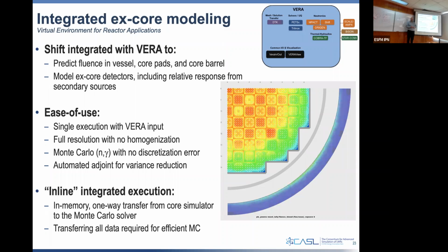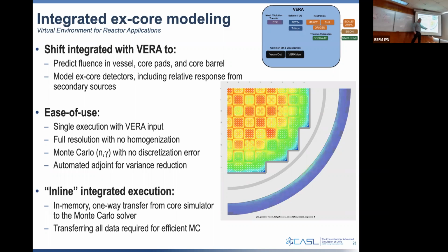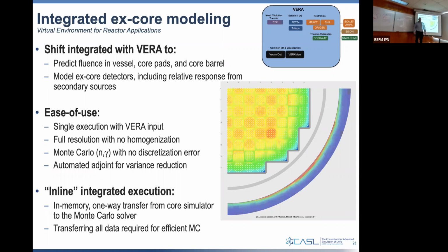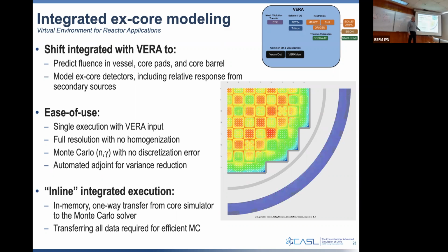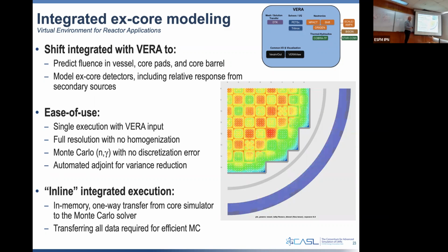So right now, most of the US reactors were originally licensed for 40 years of operation. And we talked yesterday about the coupons, the little samples of what this pressure vessel metal is. They want to know how that material changes as it's getting irradiated. And so they keep those coupons sitting on the outside, and every couple of years they take one and test it. But the reactor was designed for 40 years. Originally they said, well, we'll just take a coupon every couple of years. And then they said, let's get a 20-year extension. Let's go out to 60 years. And so most all of the reactors in the US are in the 40 to 60 year time frame.